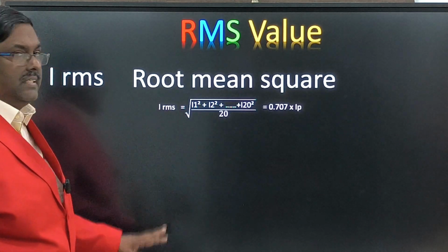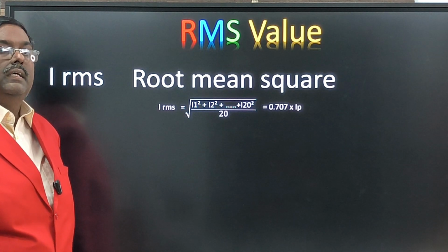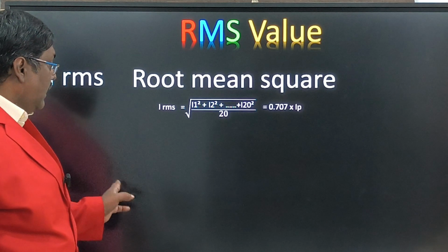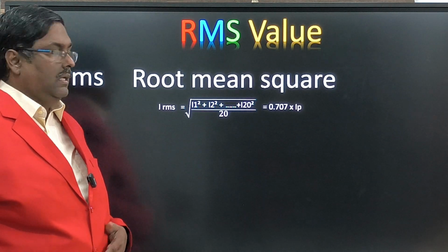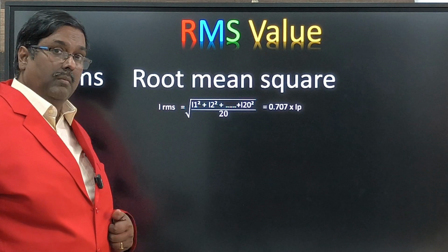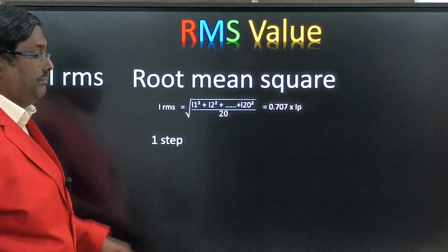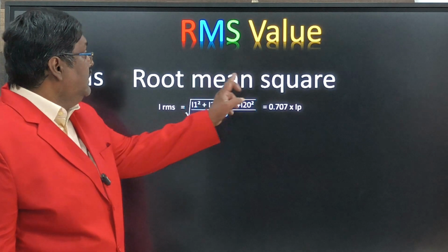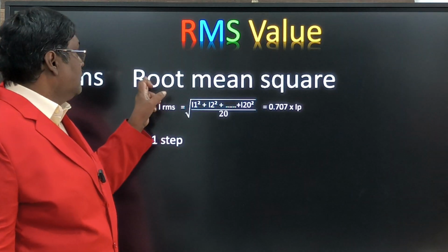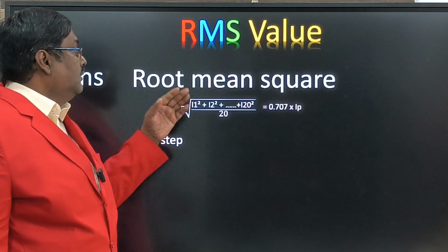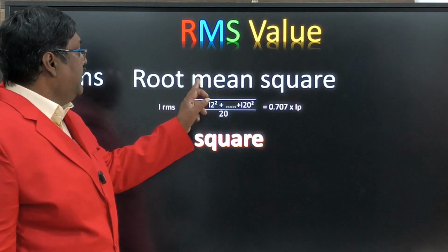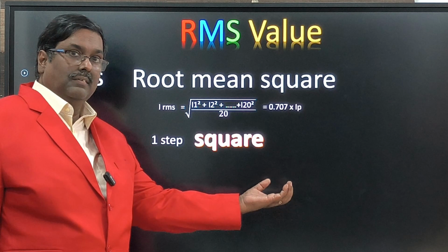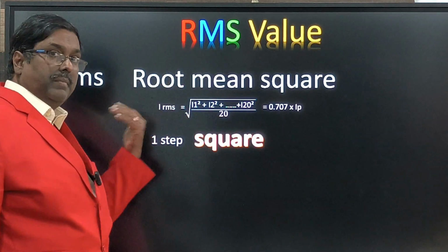So we are making 3 steps for calculating the RMS value from the curve voltages, I1, I2, I3 voltages you got now, data. From the data, how to calculate the RMS value? Here they put it in reverse. RMS means root mean square. So we have to do square first, then mean, then root. You have to do it in reverse manner.